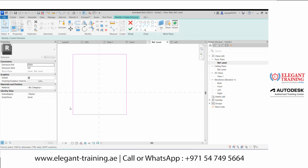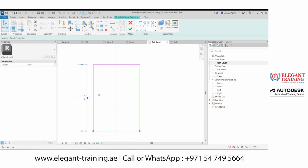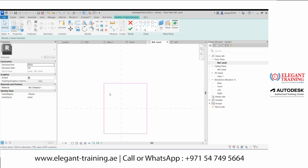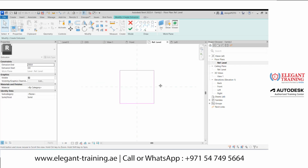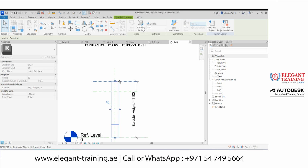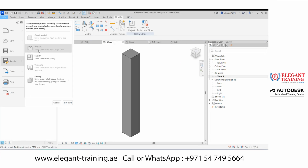Okay, but this side also I will make it 140. Now it will be equal there. Okay, to this side also I make it 70. Okay, and to make it completely one, I can mention this as 140. So now your box is in the center. Select this, you can pull it up to here and lock it. File, save as family.